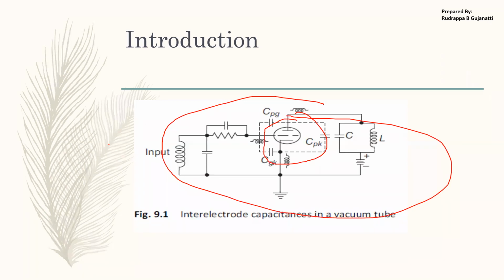So with all the adjustments, that is, we try to adjust the distance between the electrodes, that is the anode and cathode, so that the transit time can be addressed. These are a few adjustments we try to make, but at the max, we will be able to reach up to say 1 gigahertz of operation. Above that, again, it poses problems.